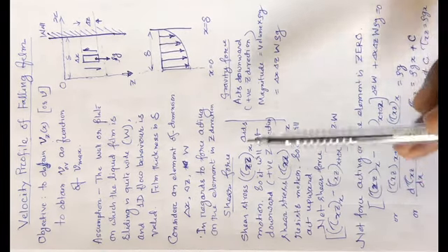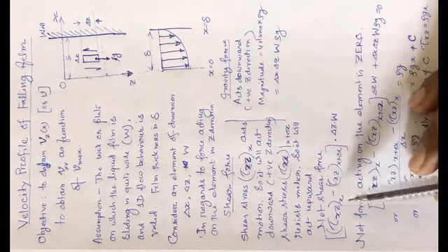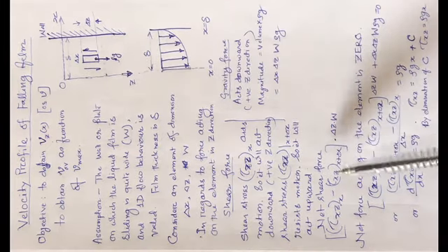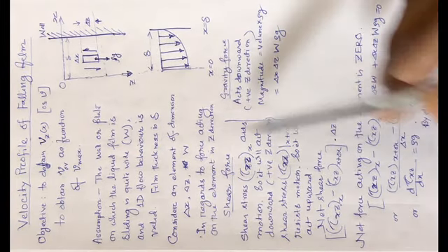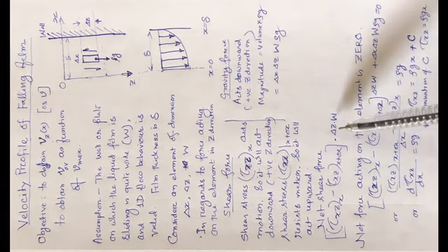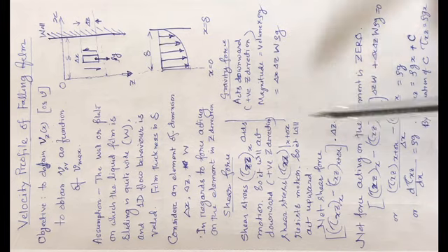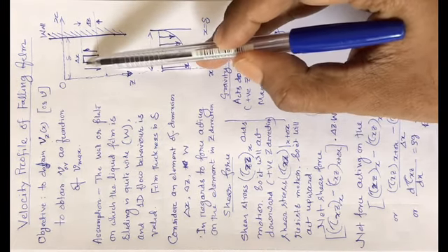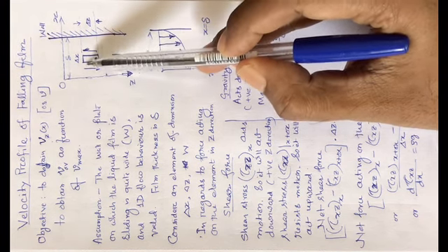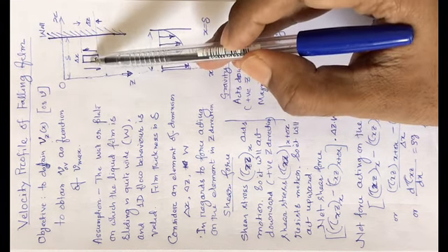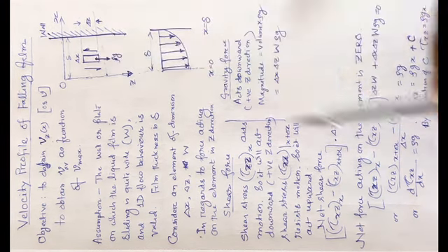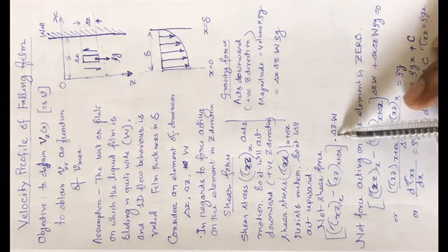So now the net shear force will be whatever is acting downward minus whatever is acting upward, multiplied by the area of action of the shear force. The area of action for the shear force will be this height multiplied by the depth across this surface, that is, the depth perpendicular to the surface of this page. That is W. So delta z into W.